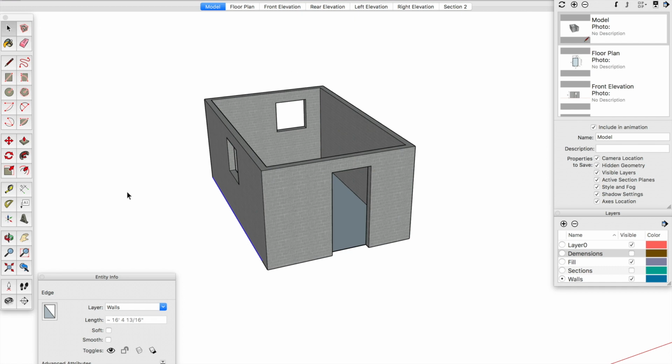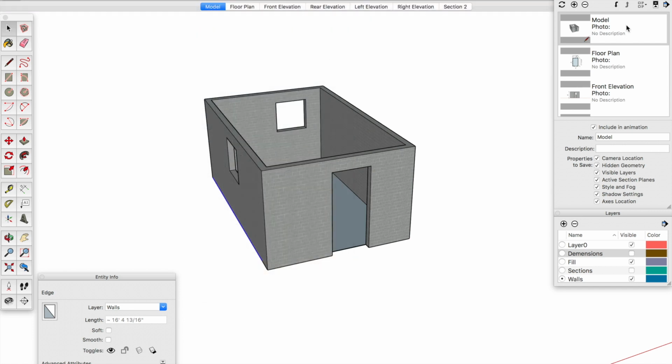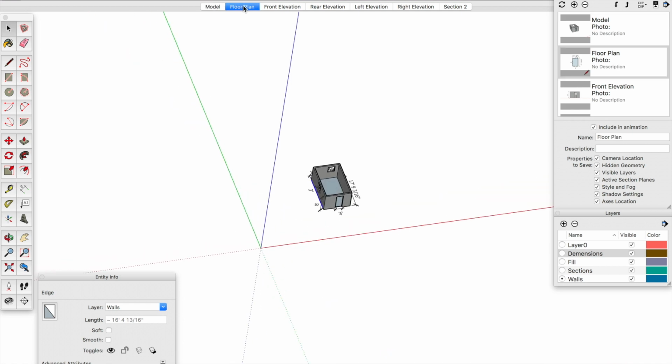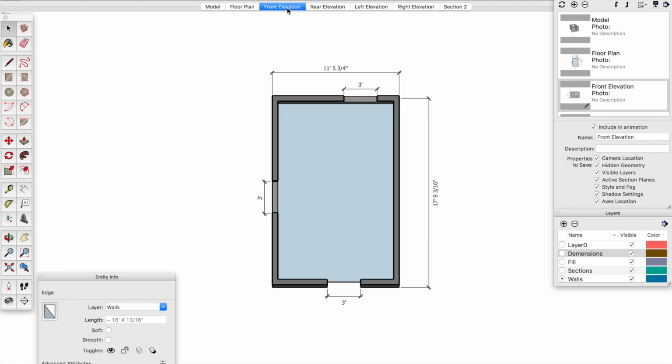And then that's what I want to get into next, which is scenes. This is the scene tool right here, and once again you can go to Windows, Scenes and turn this on. Basically how I look at scenes is like a snapshot of what I want my documents to look like. You have this scene bar up here, and you can just scan through the scenes. This very basic one is called floor plan, because this is exactly how I want my floor plan to look on my plans.